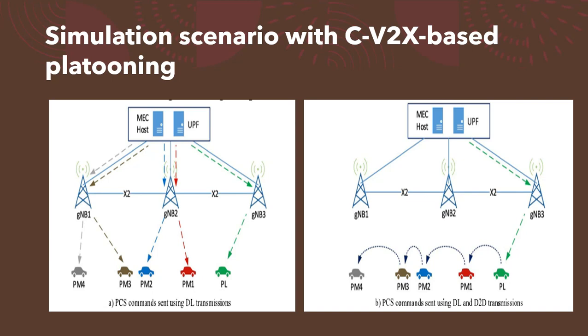The group vehicles into platoons based on information gathered by MEC applications, and a platoon control service takes as input the information formed by the PFS and computes new acceleration values that vehicles must use in order to converge towards the target.